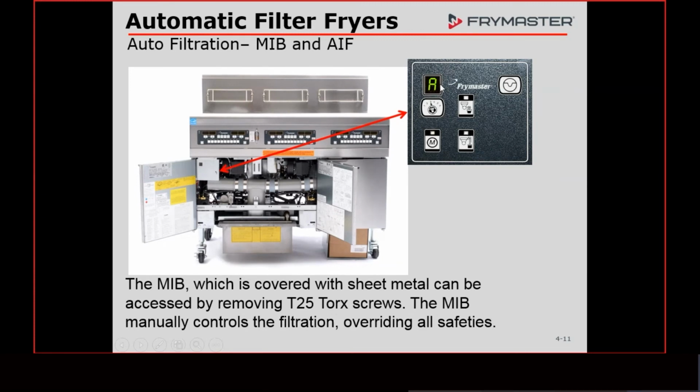Otherwise, it should be an A. Now, when you go in as a service tech and we take that shield off, that shield is held on with T25 Torx screws. There may be one, the latest versions has been one, but before that, I know that we had as many as 3 on there, 2 on the side and 1 on the bottom. But either way, it's a T25 Torx.